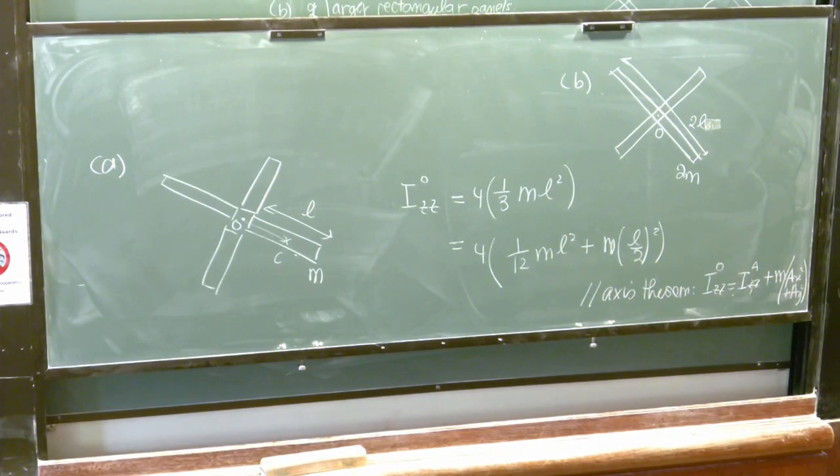But before I do that, I want to ask you, under which conditions is the linear momentum of a system, of a rigid body, conserved? When is the linear momentum of a rigid body conserved? Exactly, when the external forces acting on the system sum to 0, right? When this F dt term is 0, then G at t2 minus G at t1 is equal to 0. G at t2 is equal to G at t1. So the linear momentum of the system is going to be the same.